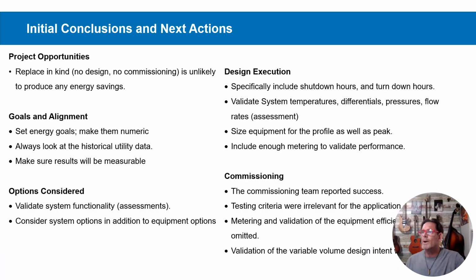So what kind of conclusions can we draw from these how-not-to-save-energy projects? The first thing that I think we've been saying all along is that replacing-in-kind projects, particularly if there's no design, no commissioning, are very unlikely to produce any kind of energy savings. At best, it's going to be a one-for-one change out that gives you one-for-one results. And what we've seen is that very often, putting in new things that consume natural gas better, you can see energy go up.